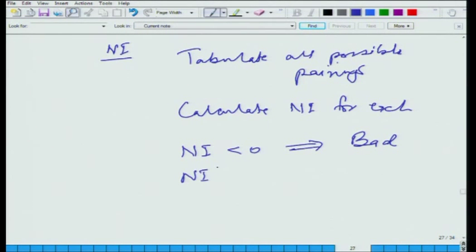If the Niederlinski index is close to 0 but greater than 0, these cannot be used, these are poor pairings.